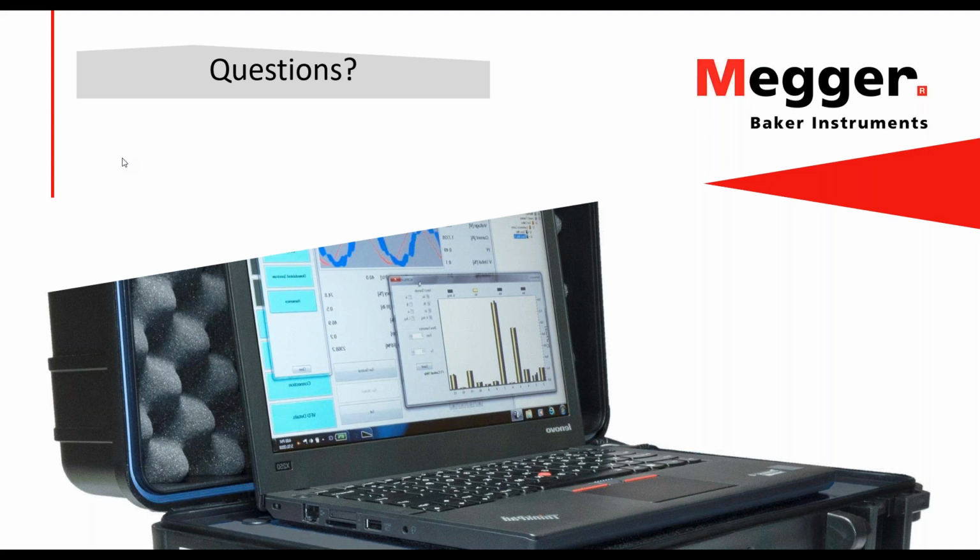Voltage unbalance in the first place creates a negative sequence component on the voltage system. The negative sequence component has a phase rotation that goes counter to the rotation of the positive sequence component, which would be related to the main voltage sequence that we have.